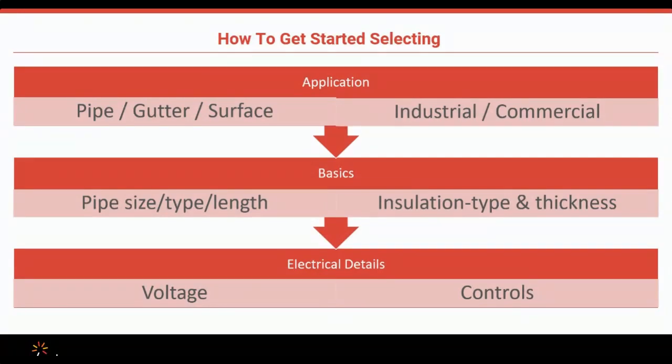And if it's a hazardous location, it's really important to understand what the area classification might be. A Class 1 Division 2 area, as an example, is what we handle all the time with our industrial components, which are standardly rated for it. But if you get into an explosion-proof area, a Class 1 Division 1 area, that becomes a completely different product offering that's rated for that application.